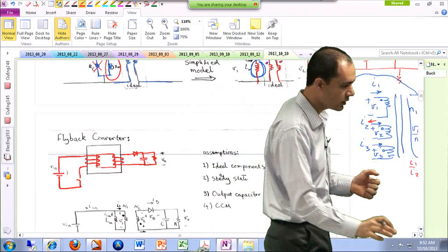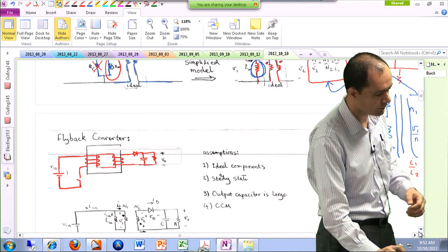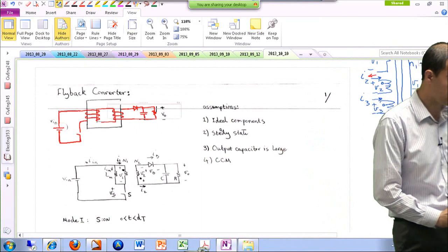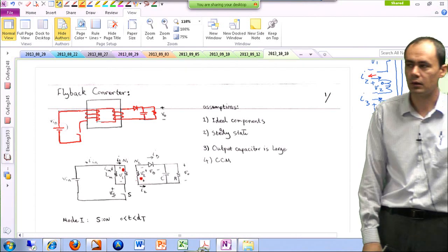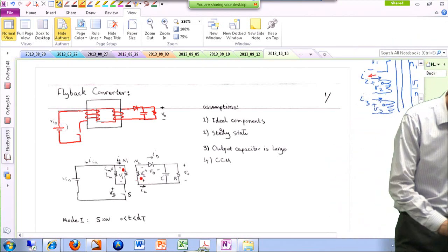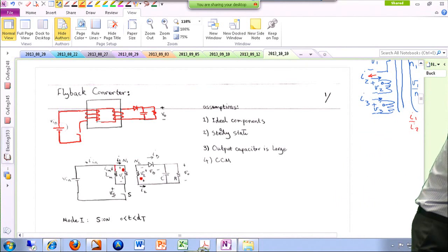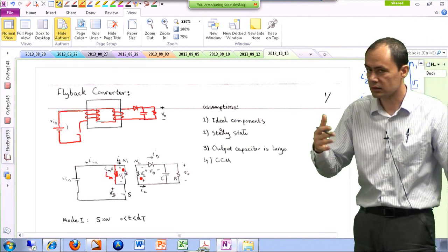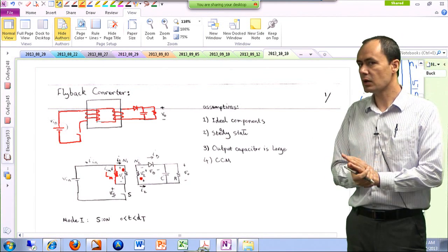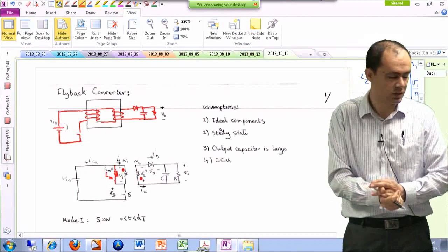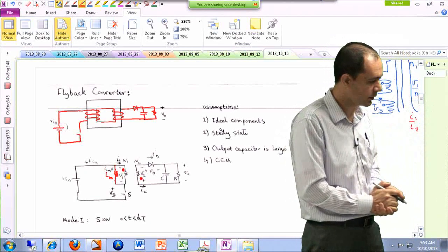So if you draw the equivalent circuit diagram, you will end up with a schematic like this. And please pay attention, the dotted nodes are configured in this way. As you can see, we are also taking care of this magnetizing inductance. We label it L_M, the inductance of magnetization. And then the rest of the system is basically the same. Sometimes they don't draw this magnetizing inductance, but the assumption is it's there. You shouldn't forget about it.